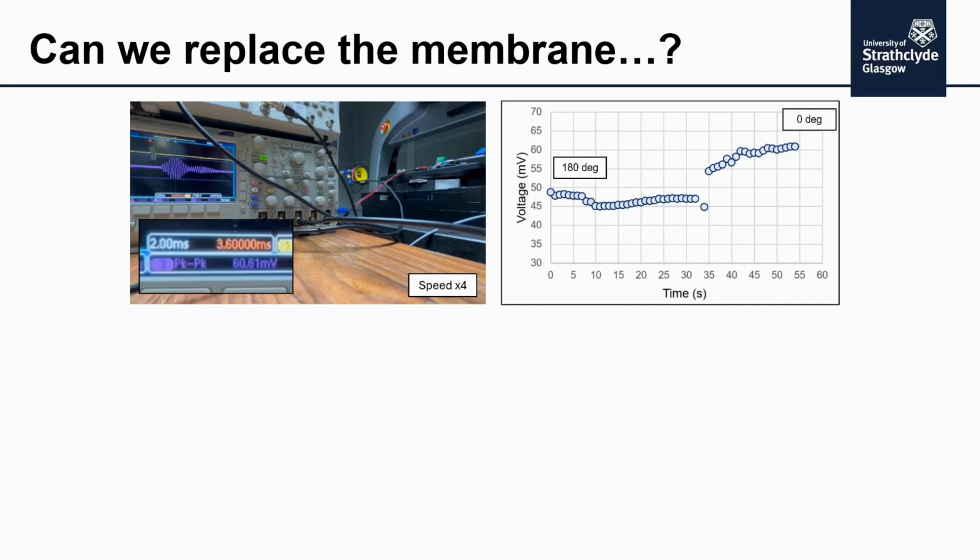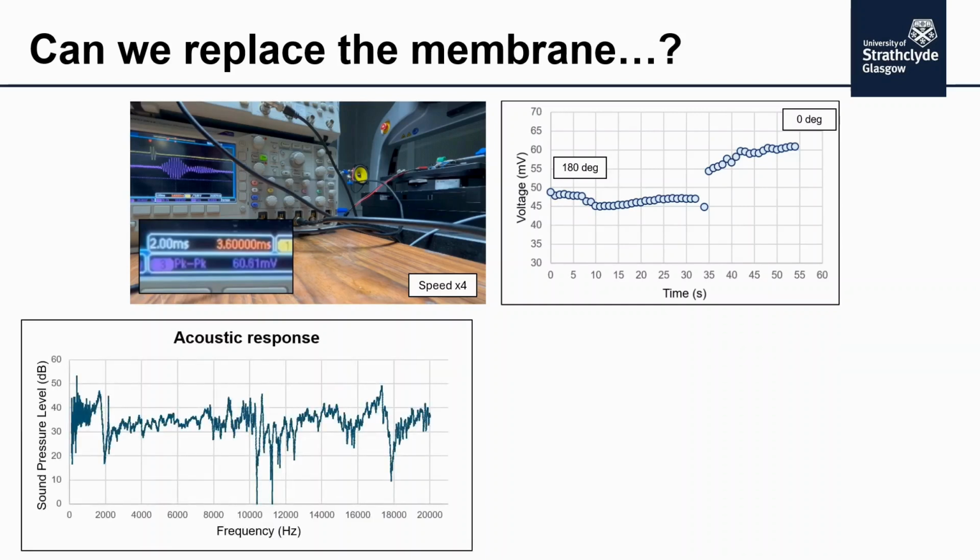If we look at the acoustic response of the unit cell, we maintain the main bandgap there, it's quite noisy, at 2000 hertz, but we see that there's nothing below 2000 hertz. Now, that's because when we are adding the PVDF membrane there, it's not really a membrane, it's acting as a plate, and believe it or not, makes a huge difference. And instead of observing undertones, we observe these overtones here, and these are dictated by other physical parameters.